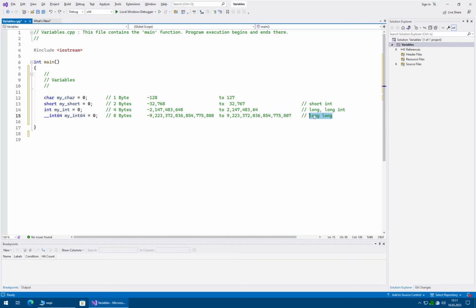Nowadays, if you are writing code for 8-bit microcontrollers like an Arduino, at least a large portion of the Arduino family, there are some 32-bit Arduinos available as well, you must keep in mind that the default integer type on these platforms will be only 16-bit.